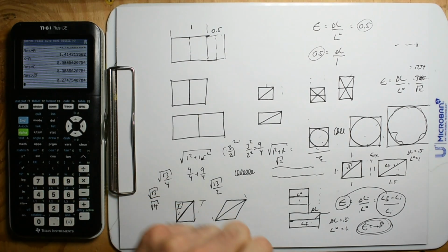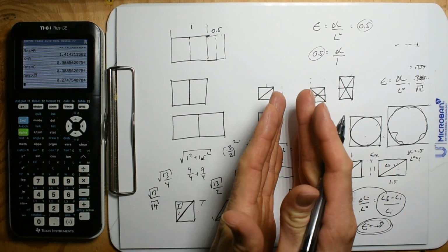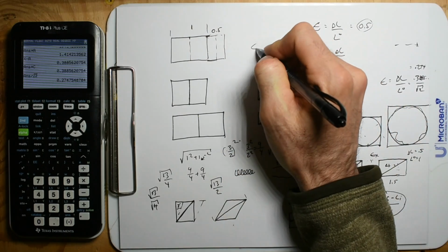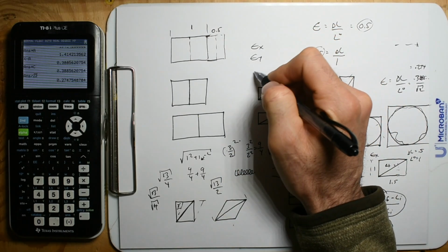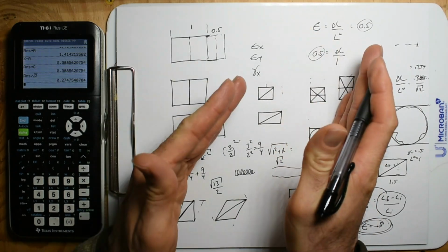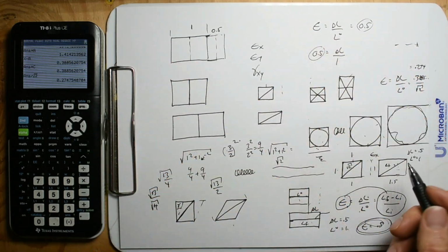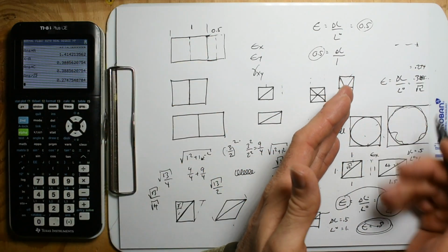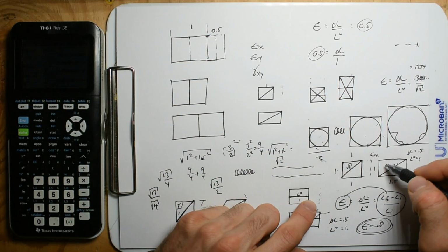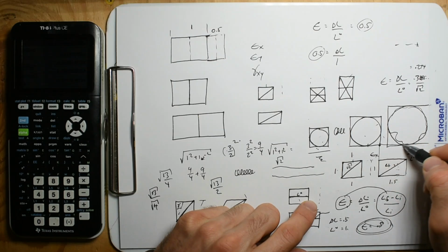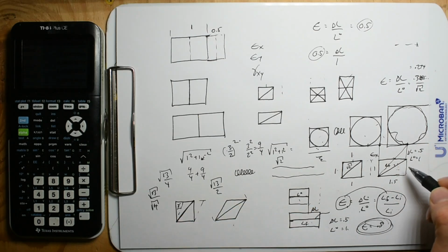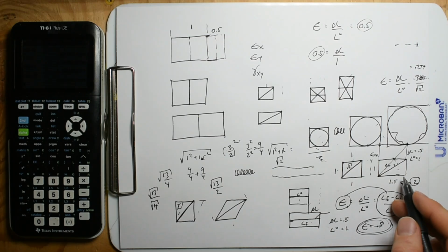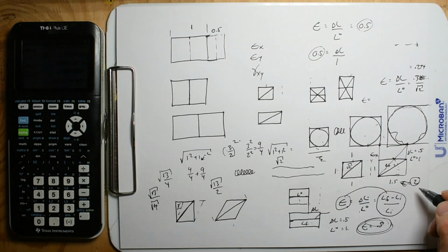All right, hell yeah. But that was in one case where we just had a change in length in the x direction. If we have a strain in the x, a strain in the y, and a rotation about the xy plane, those three elements can add up. So if I did rotate this, maybe I'm rotating it this way and then lengthening it this way, so now this diagonal lines up here, and maybe I get a strain that's 2. Initially I just had a strain in the x. Sorry, if something doubles, it's a strain of 1.